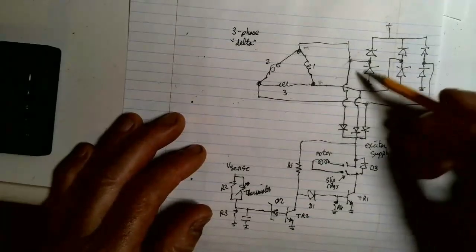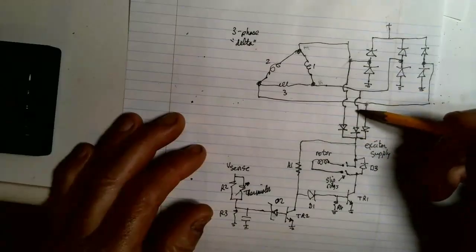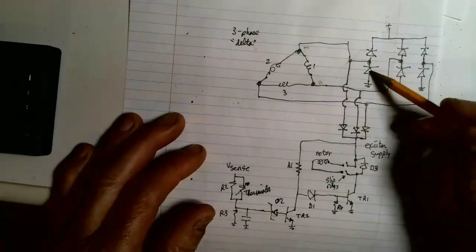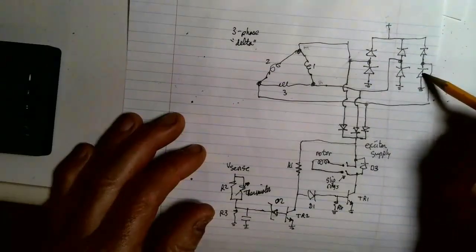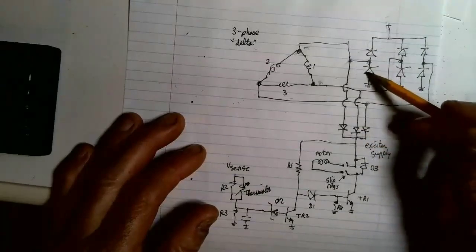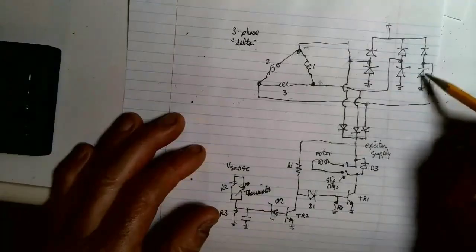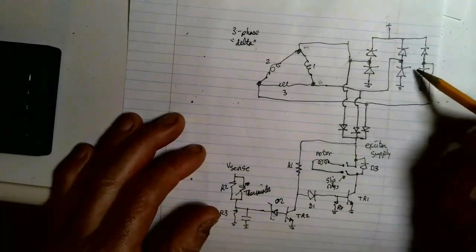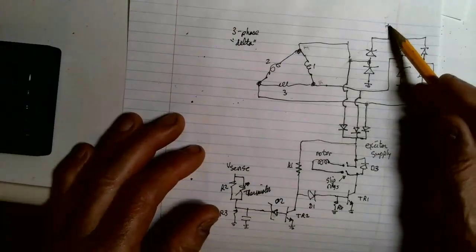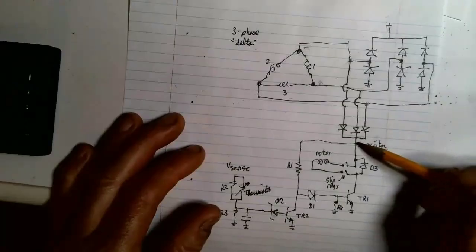So if you think about it, these 3 diodes share these lower 3 diodes here. You don't need to reduplicate. You don't need to have 6 diodes over here for the exciter supply, because you can use these diodes for both purposes. These 3 lower diodes serve both as part of the rectification for the main high power output for the alternator, and as well, these 3 diodes work with these 3 diodes to make the exciter supply.